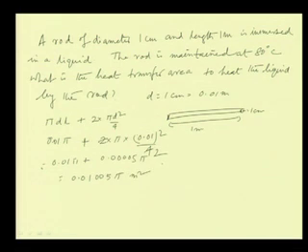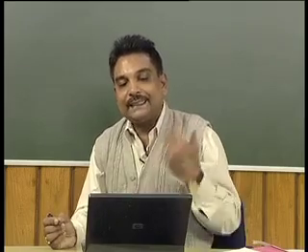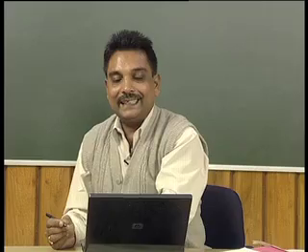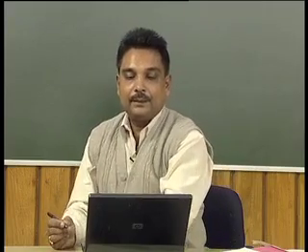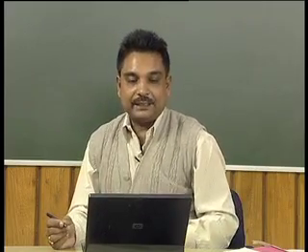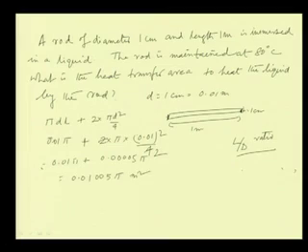Now, interestingly, what I wanted to say here is that depending upon the L by D ratio, we have to see whether we will take these end effects or not. The higher the L by D ratio, the less significant will be the contribution of the end surfaces. So, while calculating the heat transfer area, many times we neglect the surface area of the edges because of that reason.